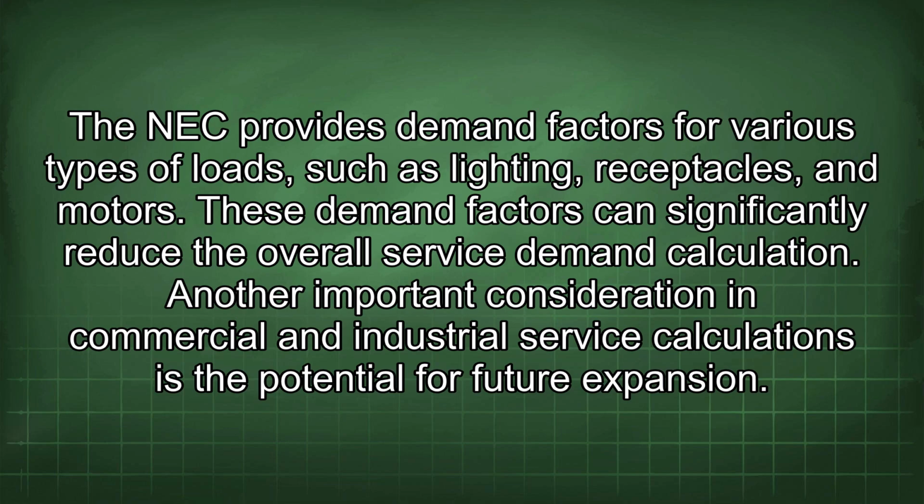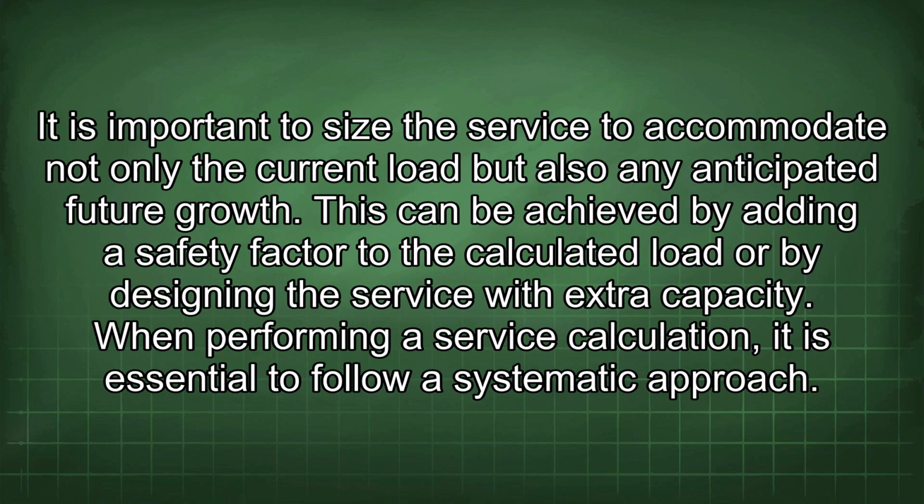Another important consideration in commercial and industrial service calculations is the potential for future expansion. It is important to size the service to accommodate not only the current load but also any anticipated future growth. This can be achieved by adding a safety factor to the calculated load or by designing the service with extra capacity. When performing a service calculation, it is essential to follow a systematic approach.